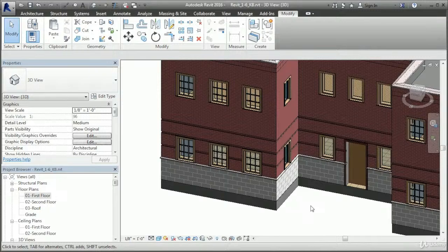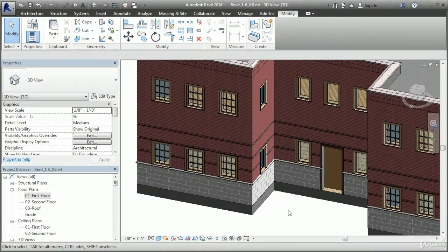System families like walls and floors cannot be loaded from a library. When we get to our doors and windows, we're going to be able to load those. But a wall or a floor or a roof type, they are going to be defined in the template. Now there's an undocumented and clever little way of transferring these elements, and it's simply to copy and paste.